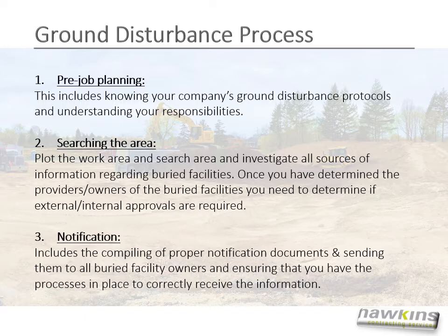Once you have determined the provider or owners of the buried facilities, you need to determine if external or internal approvals are required. The third step is notification, and this includes the compiling of proper notification documents and sending them to all buried facility owners and ensuring that you have the process in place to correctly receive the information.